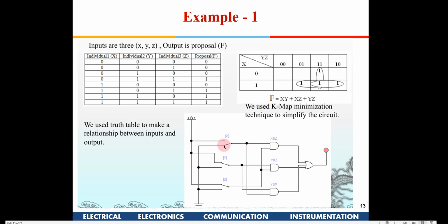If he puts it down here, you can't use this in this particular circuit like normal switches we have in our homes. If you switch it off, nothing will go. What is nothing here? If you have a wire hanging here without any input, then this particular AND gate may not give the correct answer, because the wire is hanging. So this switch has got two positions. In one position you will give VCC, and when you are switching it off, ground will be going here.